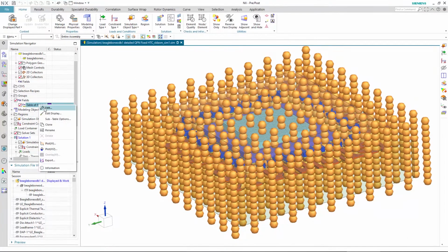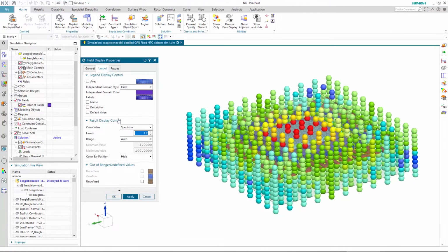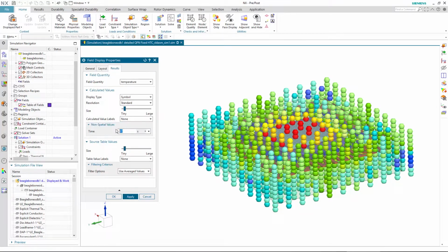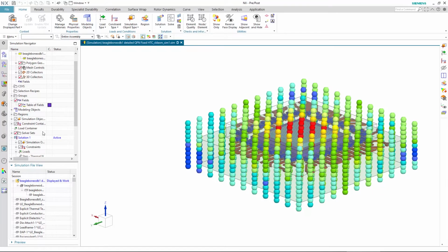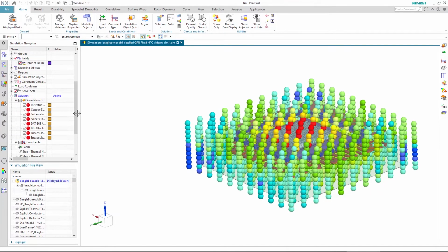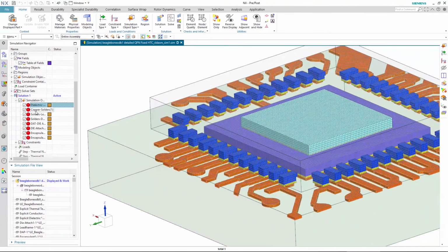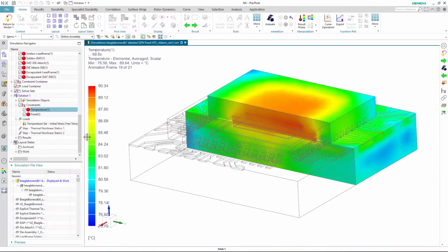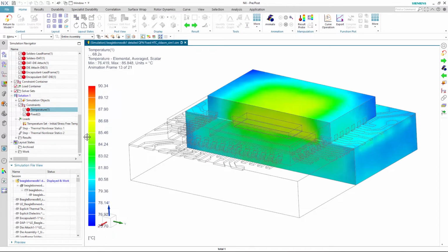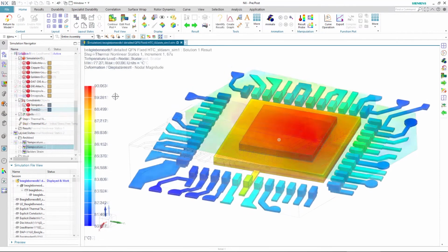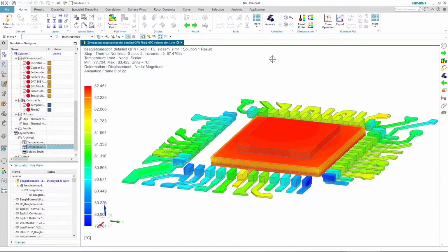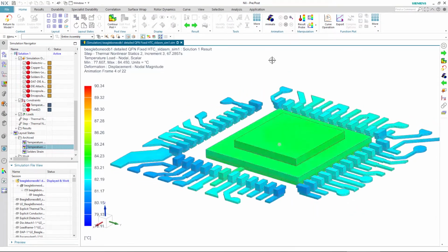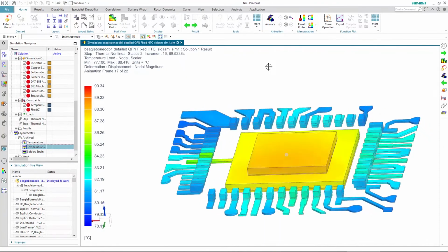3D temperature fields as predicted by FLOEFD are seamlessly mapped onto the equivalent finite element mesh necessary for thermomechanical simulation. Once those temperatures are set as load boundary conditions, then a thermomechanical simulation can identify areas of undue strain and therefore identify areas that may benefit from remedial design actions so as to minimize that strain and therefore minimize risk of reliability-based failure.